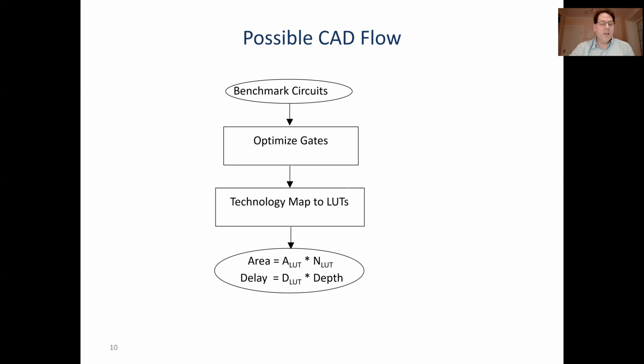It figures out that when you write this code, you want an AND gate; when you write this code, you want a flip-flop; this code is a multiplier, etc. So that's happened, and then we go into optimizing gates. That's a fairly complicated CAD problem, with lots of algorithms that try to simplify the logic and use fewer gates. We don't really have gates on the chips we're looking at. We have lookup tables.